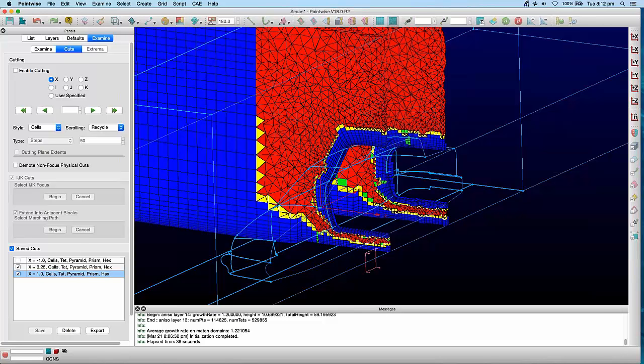So we got another one. How do you measure aerodynamic forces accurately using data and suspension? That's nice and long. It's very difficult because you have to take into account the noise in your data. You have to account for things like the roughness of the surface you're driving over, and crosswinds, especially at airports. It generally comes down to doing multiple runs back to back, and you have to take the data you get with a grain of salt. You have to be able to say, okay, we roughly know where we're going with this.